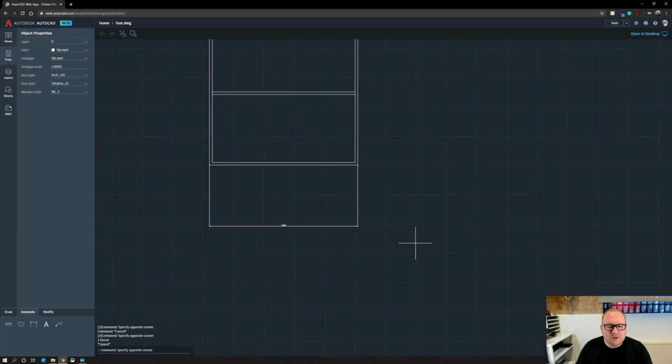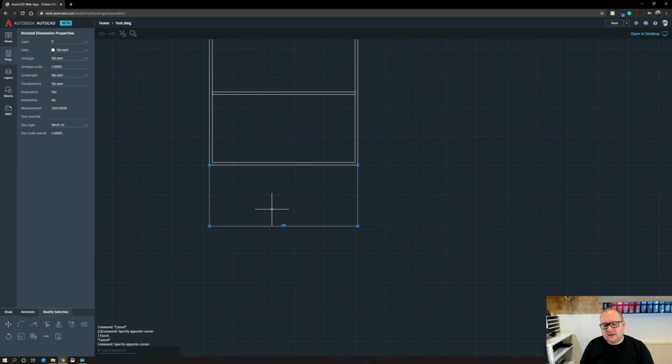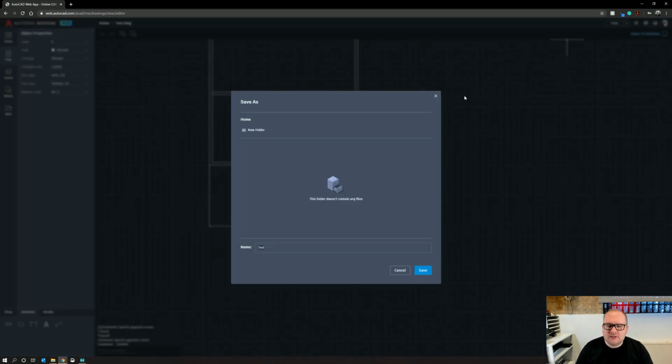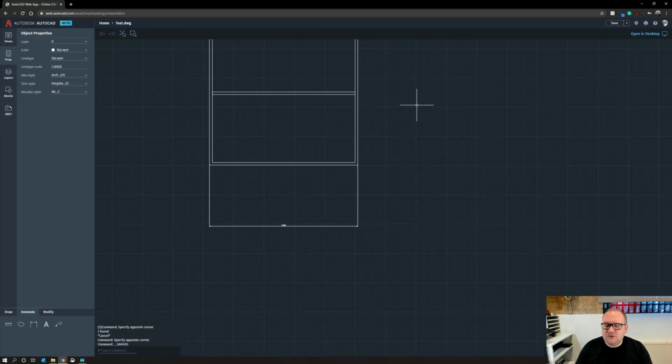So they've built some in, but perhaps it might be worth uploading a blank couple of documents just for you then to edit and resave. I'm not sure if you can do a save a copy as. Let's have a look. Yeah, there you go. You can do save as. So we can save this as a new thing. So if you uploaded a generic DWG, now you can't upload a DWT. That is another flaw. If you uploaded a template in a DWG format and then do file save as, you could then very quickly pull up your standards and your paper spaces for 2D drawings.